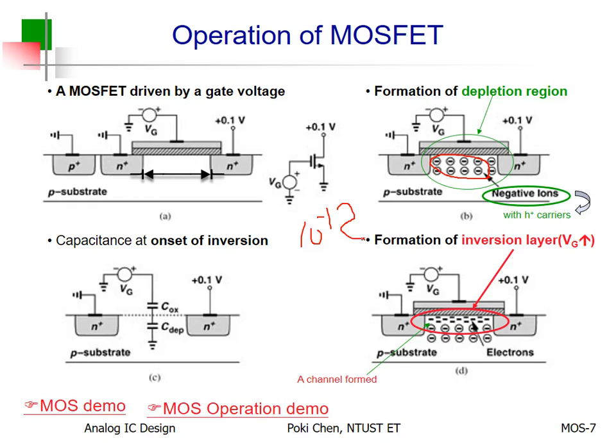From microelectronics, you learn, if you only apply VTH to the gate, the current should be 0, right? It is never true. No, it is still conductive, but very, very little, according to the conductivity of pure semiconductor, which is really, really small.